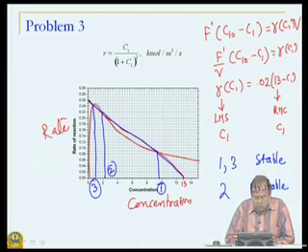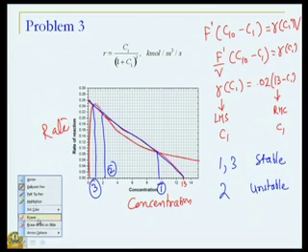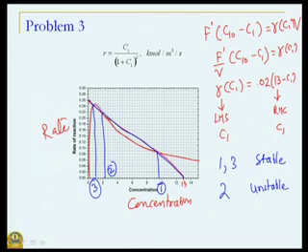Once again, how do we verify it? So, let us say that we have this steady state number 2 and we introduce a perturbation. What will happen? In this particular case, the rate of conversion of one species is lower than the rate of its net addition. So, what will happen? Concentration will keep on increasing and we will come to this particular steady state, and same thing can be argued if the perturbation is in the reverse direction.